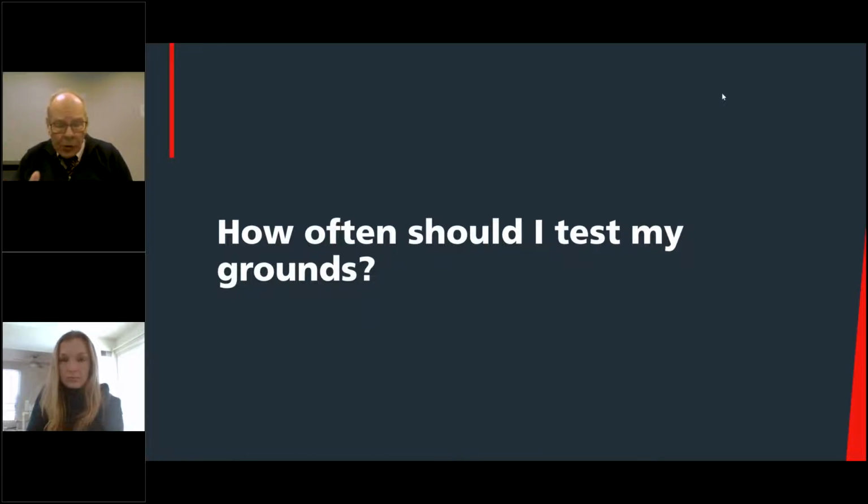You're not always going to be testing at the same time of year, because depending on where you are, your grounding can vary quite a bit around the calendar. And especially if you're up where you get hard winters, the dead of winter can be really bad if you get frozen soil. And also August or a hot, dry summer can be really bad. So you want to make sure that you're testing at those times of year, because those are your worst case scenarios.